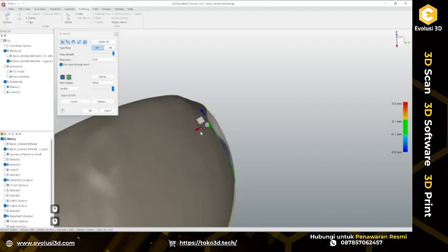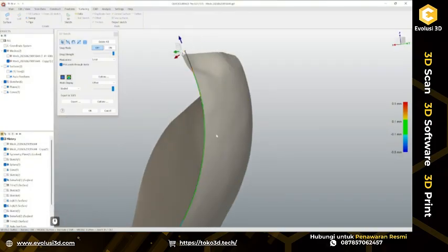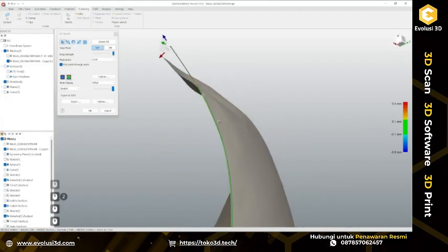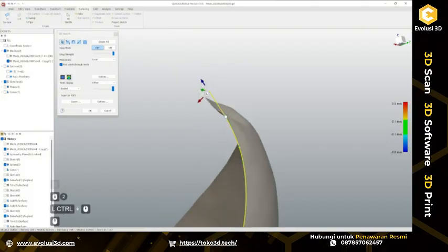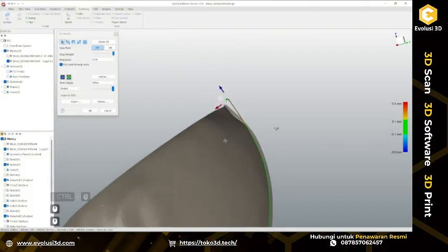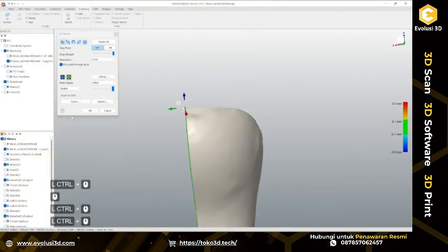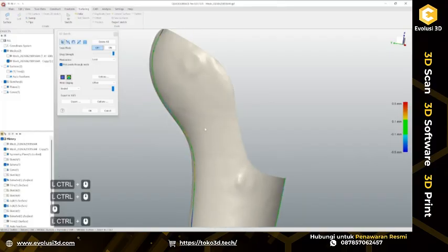So at this point, I'm just going to pull it slightly away. So my deviation analysis shows I'm good along this edge here. So it's nice and smooth, basically, as it comes out of the curvature of this blend here, it just goes more or less straight vertically. Okay, not completely okay, but yeah. Let's move to the next curve.